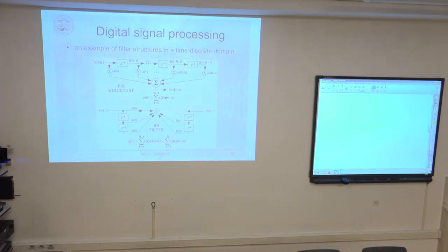And this is repeated in software. So to implement this operation, how many operations do you need? You have 5 multiplications with these coefficients A0, A1, A2, B1, B2, and 5 additions. You have to add this together to compute y of n. After that, you have this four move operations to do the state update, and you are ready to do the processing of the next step.